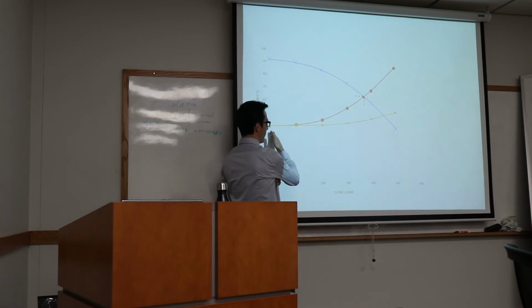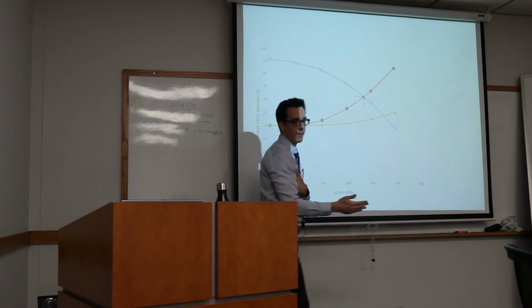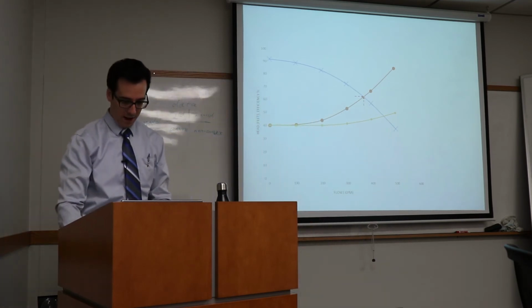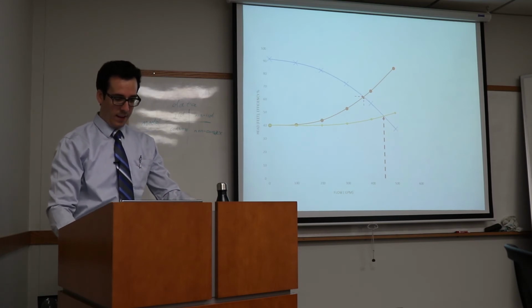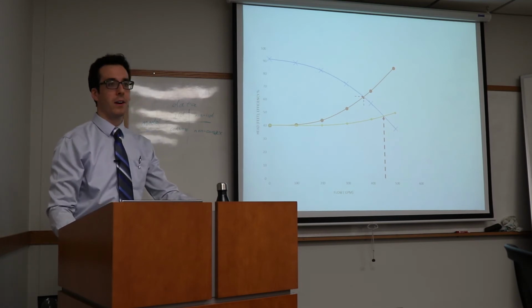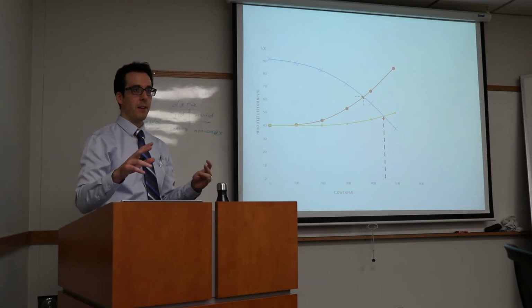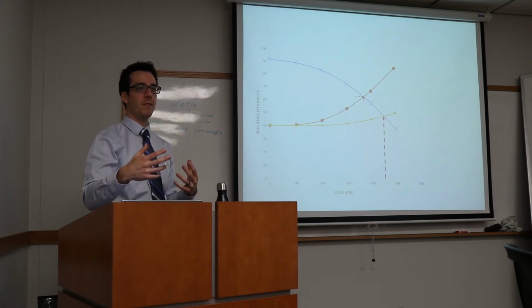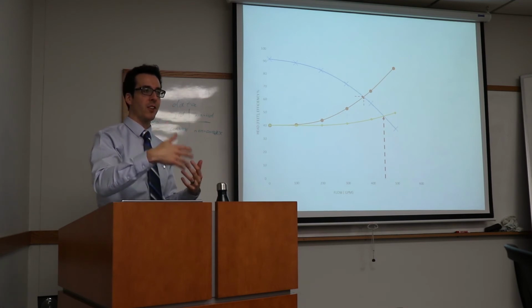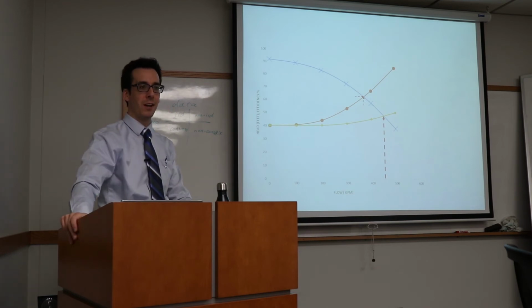That explains why with the same pump curve, we're getting different response in the performance, because we're over there closer to 450 instead of at 370 where we thought we were before. So this happens all the time, that we're too conservative in the system curve, and those changes propagate throughout the design until you get something that's way bigger than it needs to be.